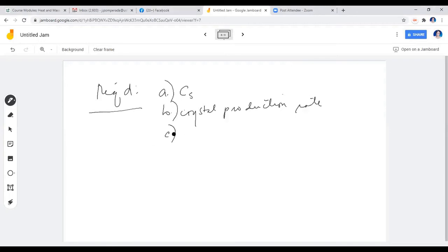And then we have, this is crucial, this one. The percent of nuclei removed in the discharge by the time they have grown to 100 micrometer. Percent nuclei removed. So size is greater or equal to 100 micrometers. So they will only be removed if their size is greater or equal to 100 micrometers, meaning this is the size requirement.